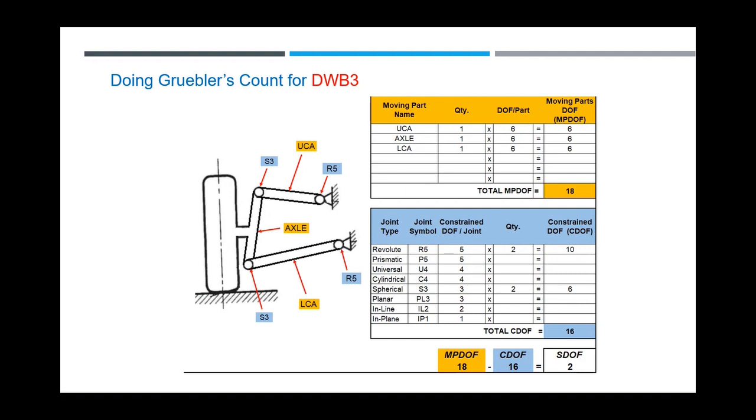One thing that's nice about this mechanism is that you can handle torques better in this direction because it's spanned between the two distances here. Whereas the other one, the torque is taken up just by the lower arm alone, whereas the top one is following the direction, right? So those are two differences.